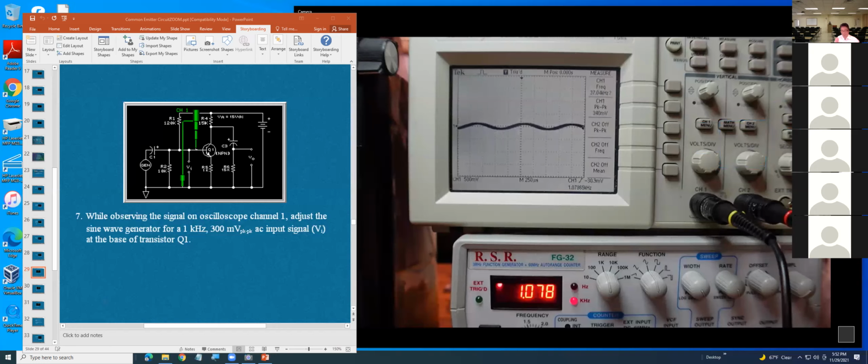When you already pull the 20 dB, that is all they give you, so you can get around 300 millivolt peak to peak. If you want more, I will show you how to do it. For example, 100 millivolt.